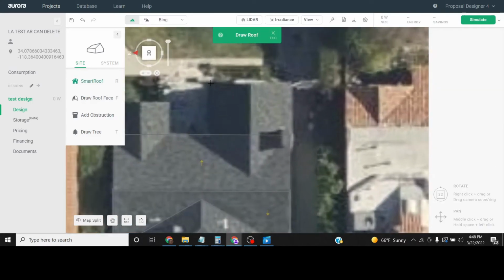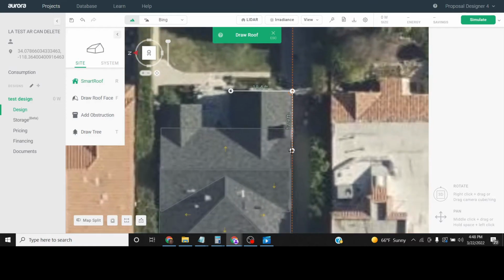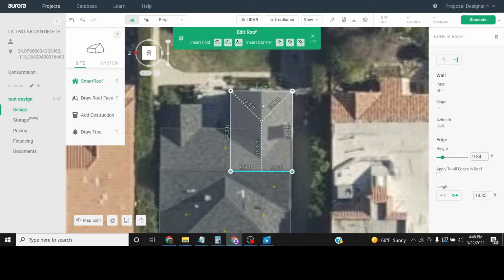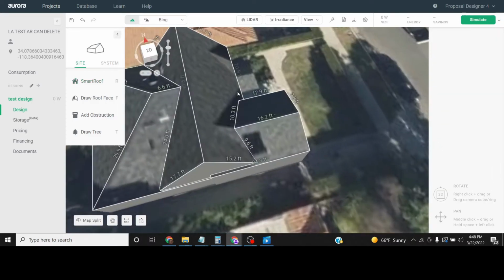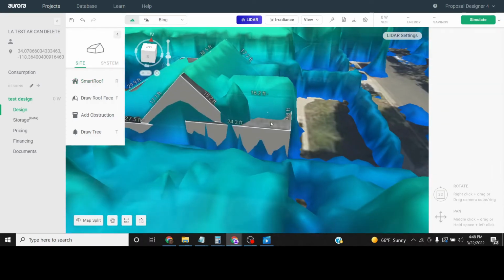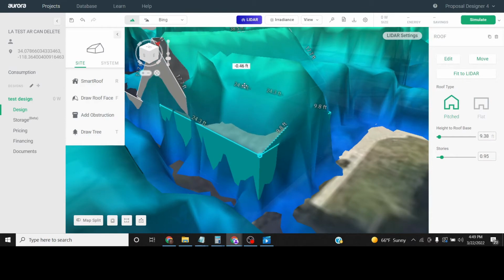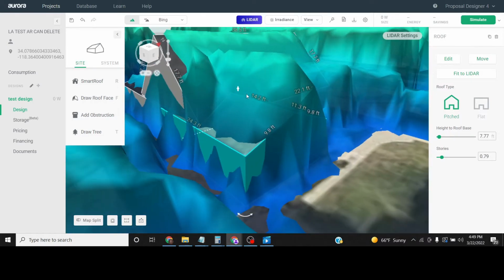What I like to do is I just like to design the roof like usual, just like I did with the other roof faces. So I'm just going to make a square, delete these along the ridge line, and the pitch is going to be a little different on this too, probably 7/12 or 12/12. We'll see. Same concept here. We drop this down till the eave starts to match. Now this one's a little difficult. I think it's probably about right here.